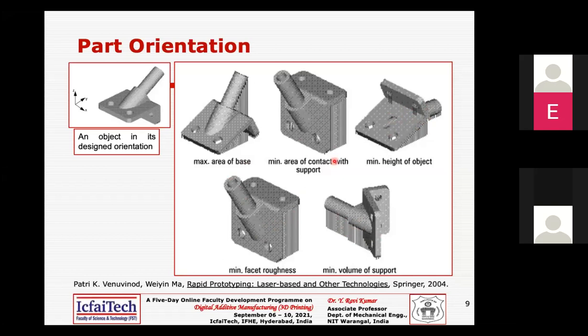So like that, we can come out with these practical examples of how you choose your orientation. But you may doubt whether you have this flexibility or option. The software by default may suggest some orientation. That may probably be the minimum Z height criterion, which is more towards minimizing the cost. That is by minimizing the Z height, that is, by minimizing the number of layers.